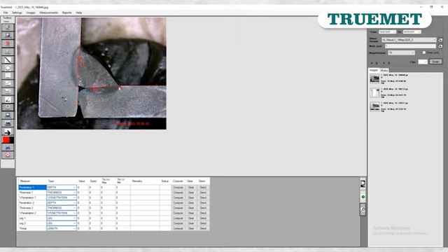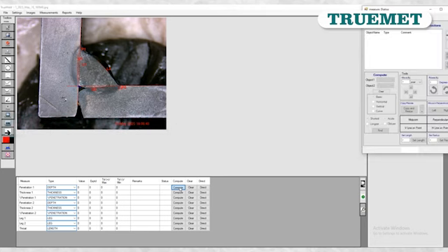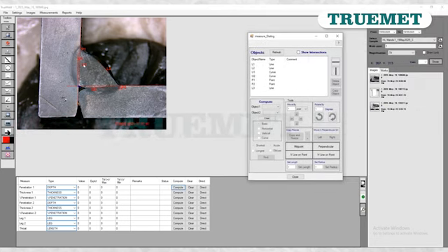Using the point tool for leg measurement. Going to use the line tool again for throat measurement. Now going to input all values. For that I am going to use compute. So my penetration 1 is from leg L1 to U1, which is also the longest distance. So in object 1 I am selecting L1, and in object 2 I am selecting U1, and here longest find. See, this is my penetration 1 distance.